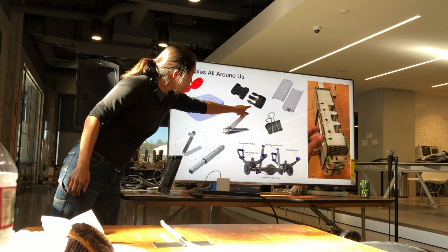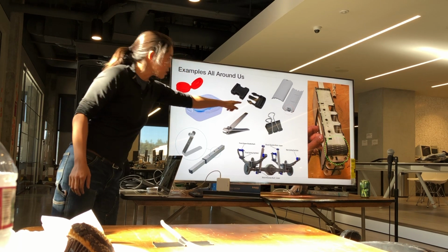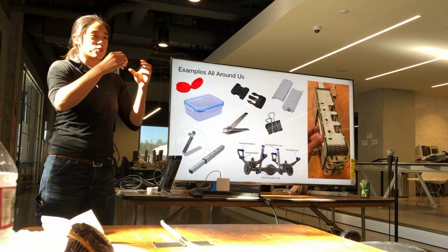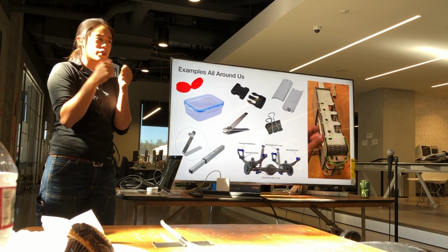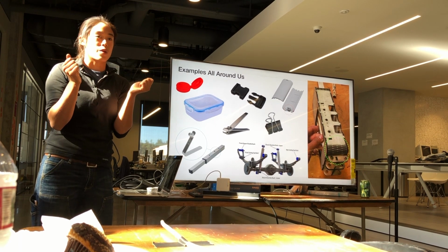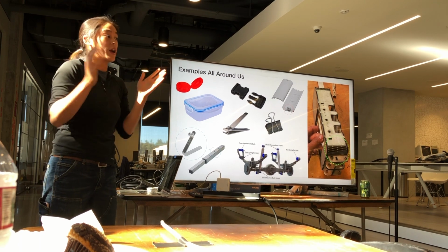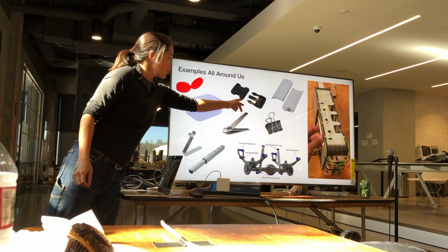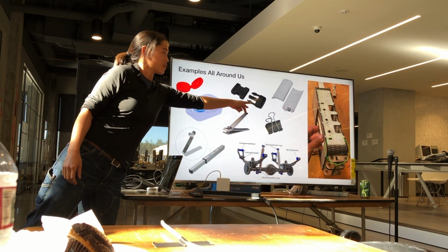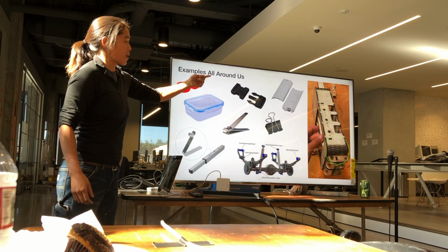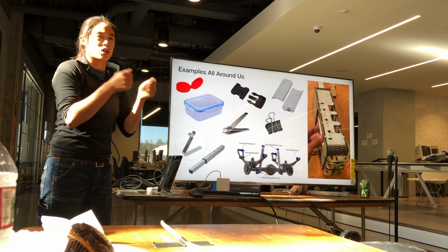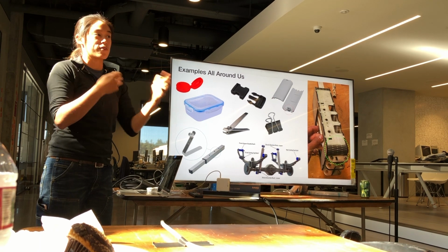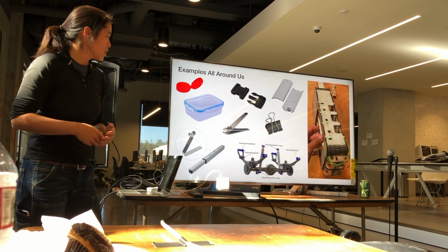Whereas for something like this buckle here, as you clip it in, you want there to be spring force for a moment, but then when the buckle is in its clasp state, you're not really relying much on the mechanism applying force to anything in order to function. And so that's cool to think about, why it makes sense to make this out of plastic, because as I said earlier about the creep, it's not experiencing a constant load, and that's what's going to make mechanisms that have a longer usable lifespan.